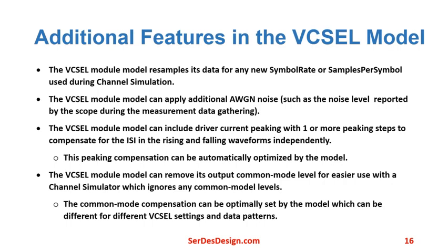The VCSEL model can remove its output common mode level for easier use with a channel simulator, which ignores any common mode levels. The common mode compensation can be optimally set by the model, which can be different for different VCSEL settings and data patterns.